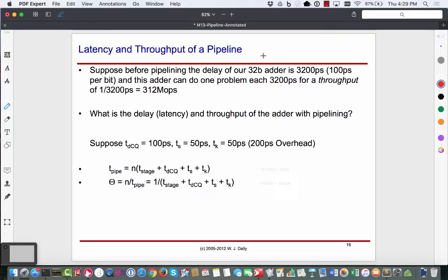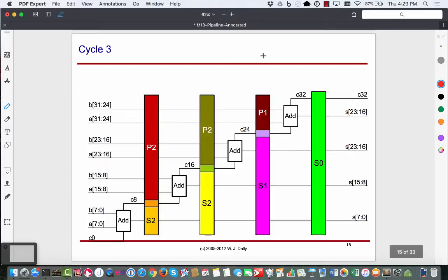Can you explain again why the clock frequency will increase by doing parallel? So what decides the clock frequency? Remember, the clock frequency is decided by, for every flip-flop to any other flip-flop, what the combinational delay was. Recall that setup timing constraint, which we saw last lecture. So the frequency of the clock is determined by the worst case path through my circuit, which starts at a flip-flop, goes through combinational logic, and ends up at a flip-flop.